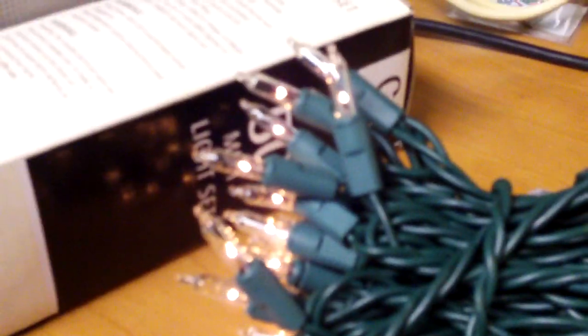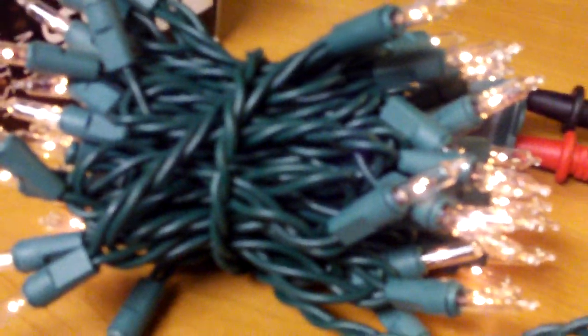And if you don't turn it on again for the next cycle, it will remain off. If you turn it on halfway through the cycle, you're able to basically get dim lights, which is what I have here. I have a set of Christmas lights set up, and they are dim. If you look at the voltage that's going to them, it's about 30 volts.